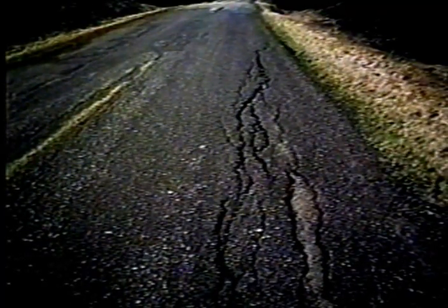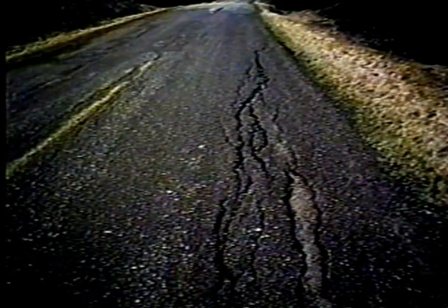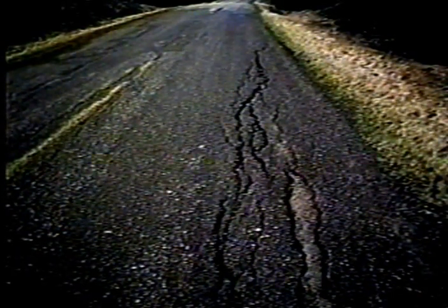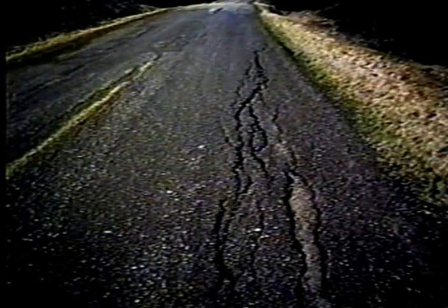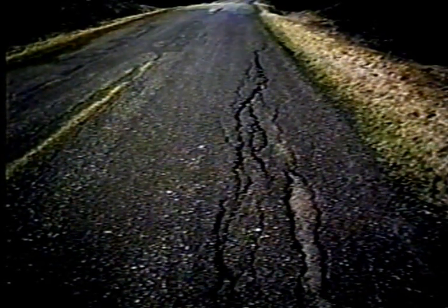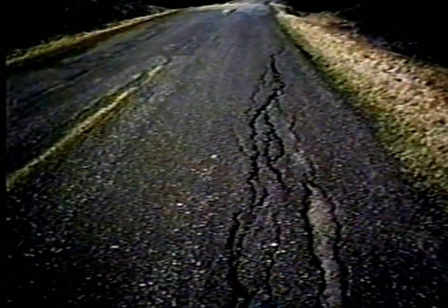Frost heave is very common in the northern parts of the United States. Here you have an example of an area that has very deep frost penetration in the center of the roadway. And quite often we have our snow piled up on the shoulder and the edge of the road that provides some insulation. So you have the center of the road heaving up more than the outside edge of the road. This can cause a longitudinal crack or distress, very typical of frost heave conditions. In addition, after the frost leaves the roadway, it doesn't always settle down into a nice smooth pavement surface anymore, and you can see rather severe distortion due to frost heave in this particular slide.